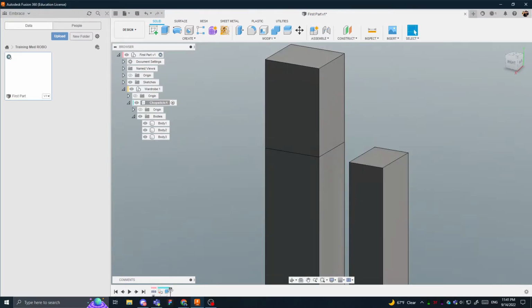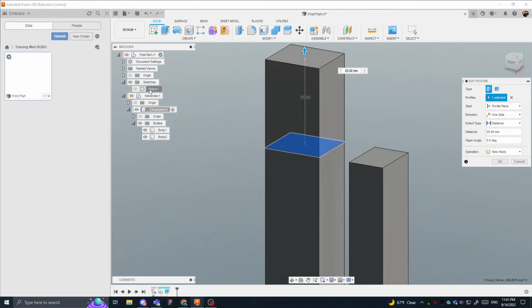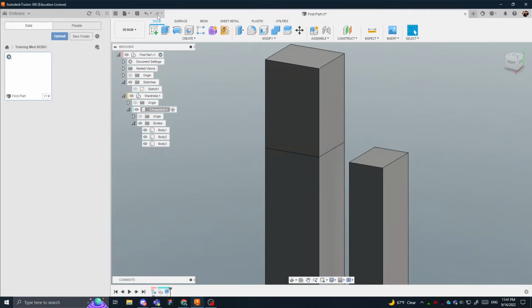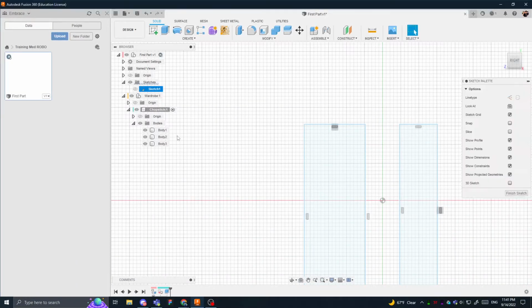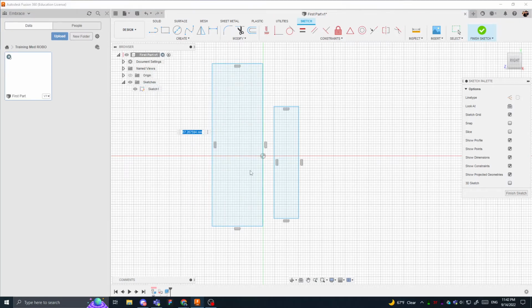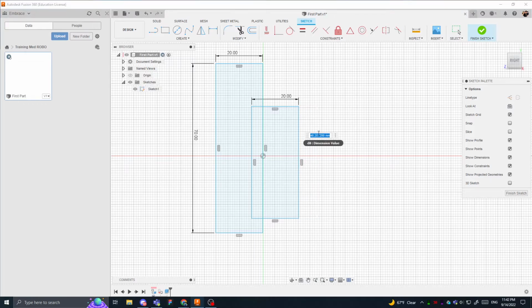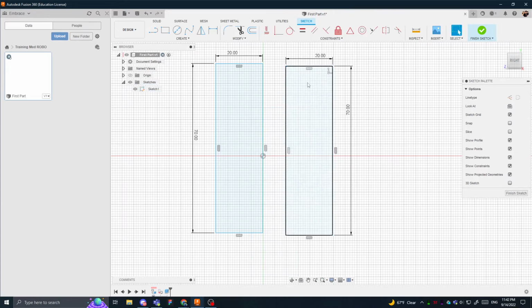If I go to sketches and I just, hold on, let me close this. I'm not in the interface anymore. But if I go to sketch and I just double click quickly, I can edit that, and notice that I can update this. I can put dimensions, so D for dimensions, and this is your main power tool. So let's say 70 by 20, and then we'll also make this 20 by 70. And you can just drag this around. Once it's fully dimensioned, everything should turn black.